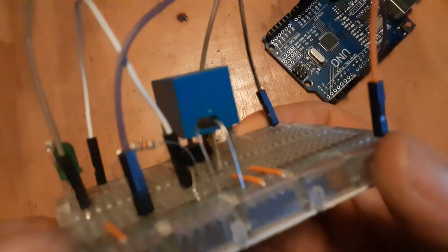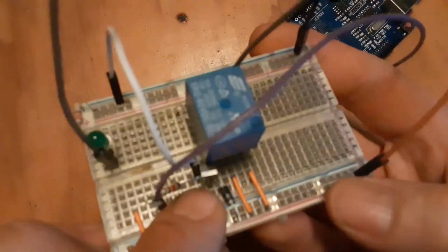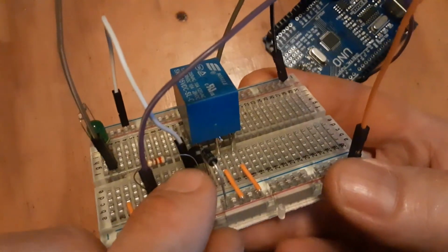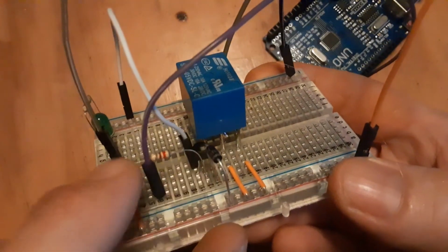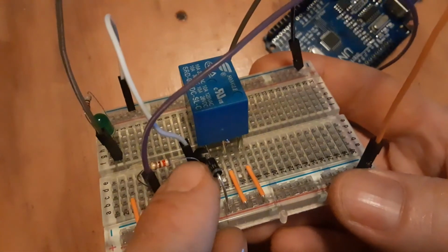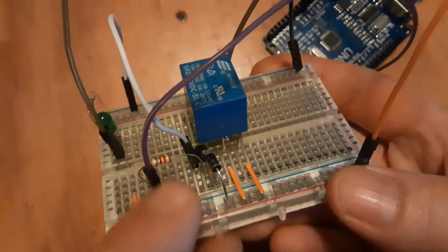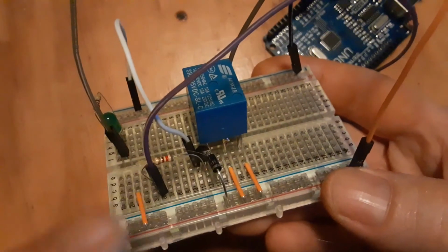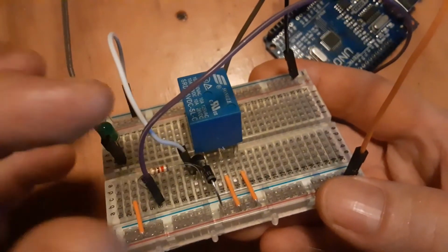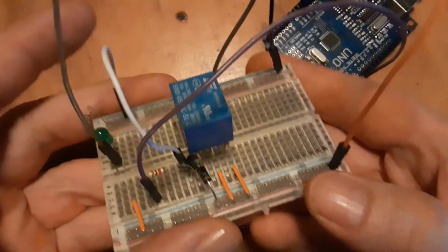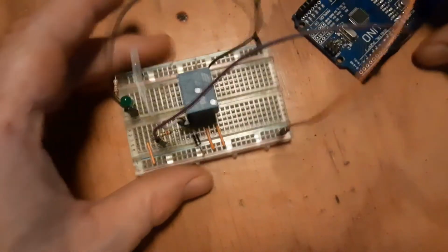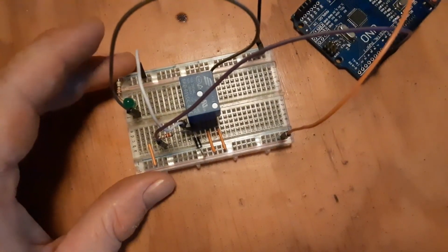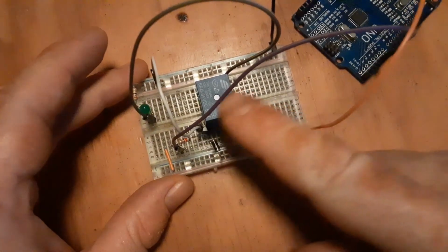So another use for transistors, besides switches, you might notice a transistor here, is we can also use transistors as amplifiers. So I have a transistor here working as an amplifier rather than a switch, just to get more current flowing through that coil and produce a better magnetic field to operate that little lever quicker. A second use for transistors, but we're talking about switches here. So a relay for a switch.